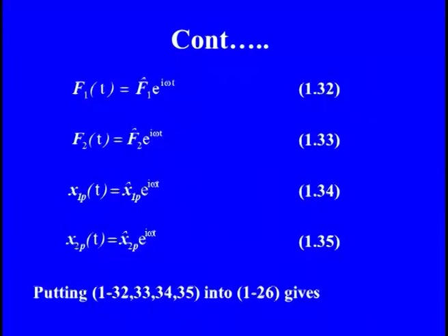So with that, you see here we can say that our force inputs F1 and F2 are showing simple harmonic motion. So we have F1, which is the time-bounded force, so it is F1 e to the power i omega t. The force 2, which acts on mass 2, is equal to F2 into e to the power i omega t. So we have both the forces, and then we can expect the outcome in terms of the steady state formulation, or we can say the particular integral.